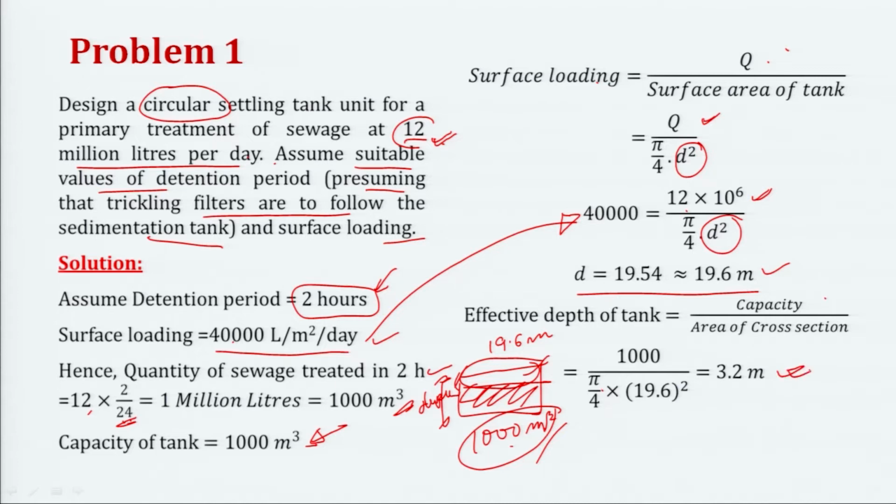So, plus, always give a free board of 0.3 meter. Let us give a free board of 0.3 meters or 0.5, whatever free board.